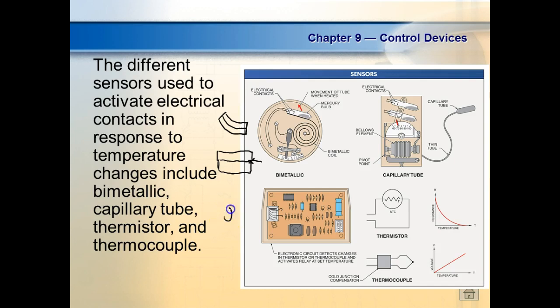Now, if we put that thing in a circle like this and cool it down, it would have a tendency to close the circle down, right? A coil in. If you heat it up, it would tend to uncoil. And this is what they're showing you here. So that's what I showed you a while ago. Here they're using a mercury switch. And then, of course, when this heats up, what does it do? It wants to uncoil and would cause the mercury switch to tilt and close the switch.